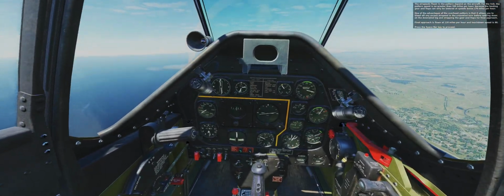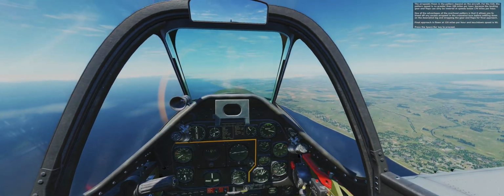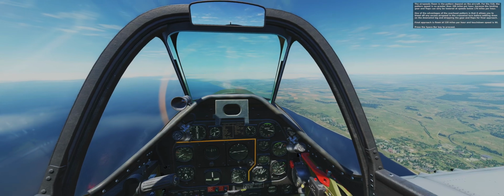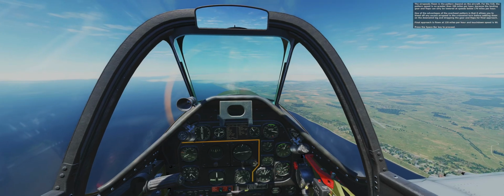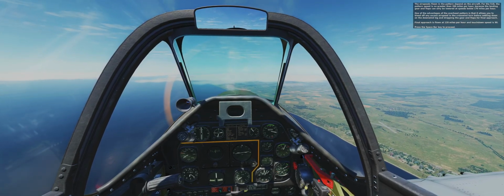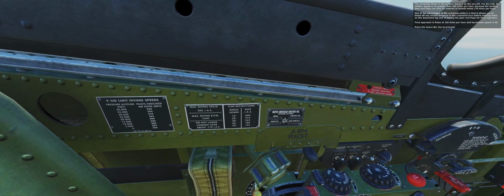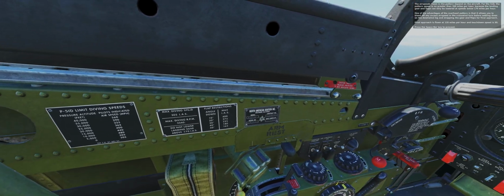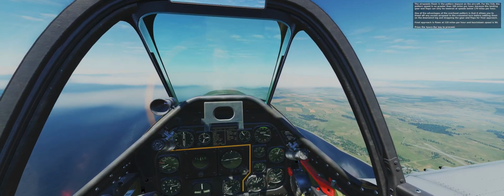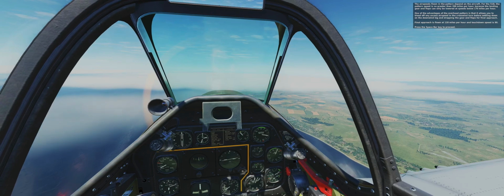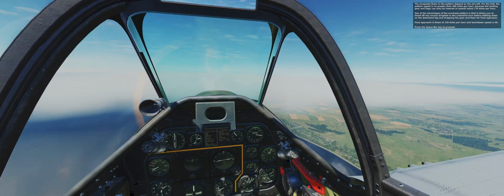The airspeeds flown in the pattern depend on the aircraft. For the P-51D, the pattern speed is no greater than 200 miles per hour, because the landing gear and flaps can only be lowered at speeds below 170 miles per hour. One of the advantages of the overhead pattern is that it allows you to bleed off any excess airspeed in the crosswind turn before settling down on the downwind leg and dropping the gear and flaps for final approach. Final approach is flown at 120 miles per hour, and touchdown speed is 90. Press the space bar key to proceed.